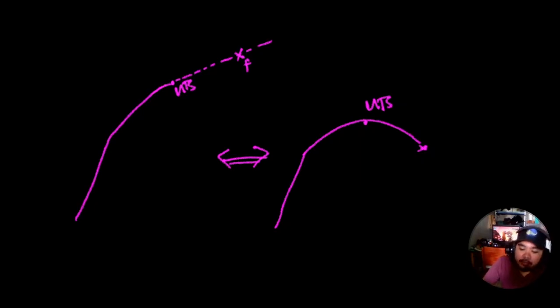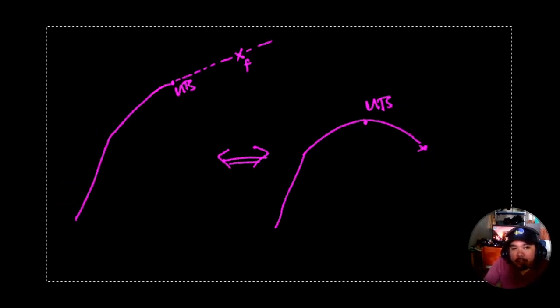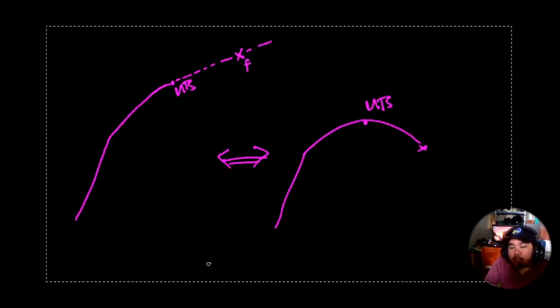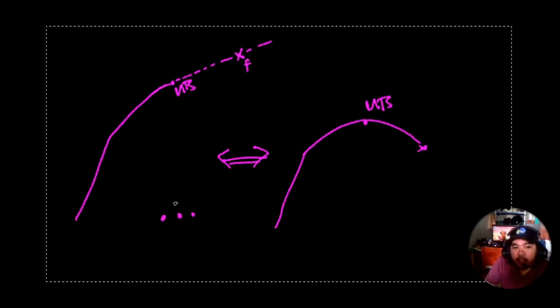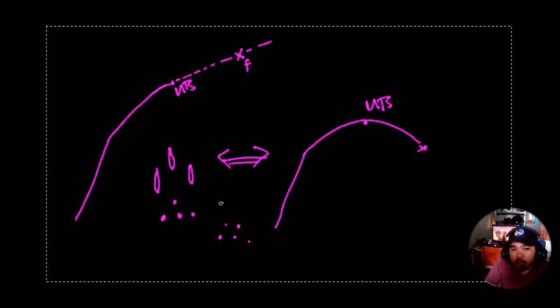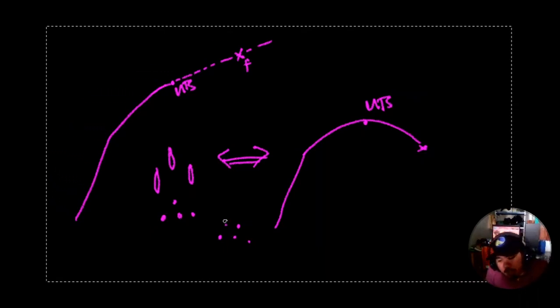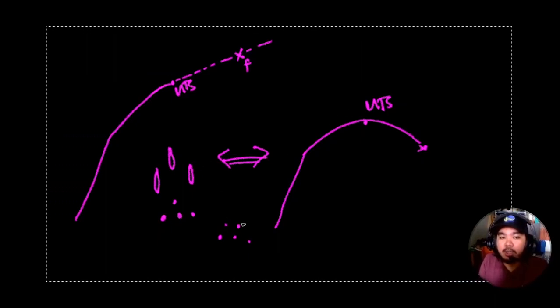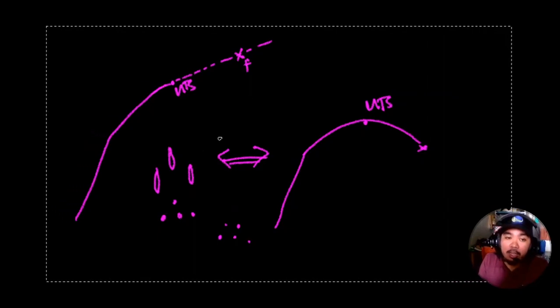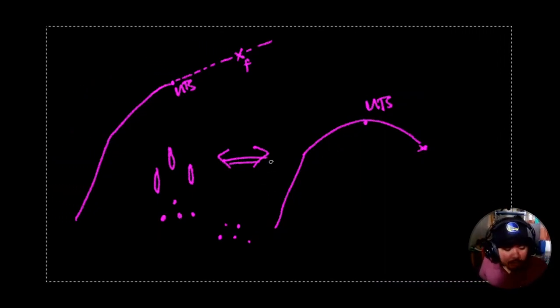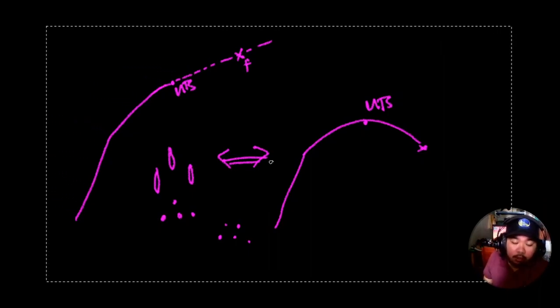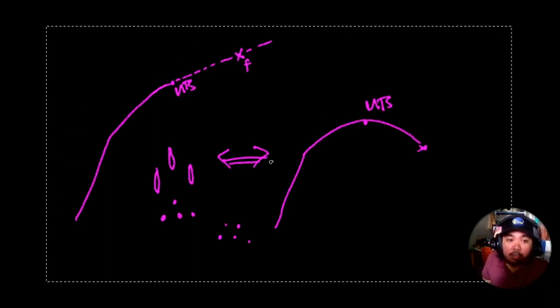Pwede pa rin. The thing about compressive loads is that they are not as susceptible to failure as compared to tensile loads. When we have tensile loads, we get microvoids, and those microvoids elongate and eventually increase. But in compression, when you start experiencing microvoids, they do not have the same negative impact as in tensile loading. So it is okay to use, for the allowable roll gap question, past the UTS. In general, as you might have heard in previous classes, metals are always stronger in compression than they are in tension.